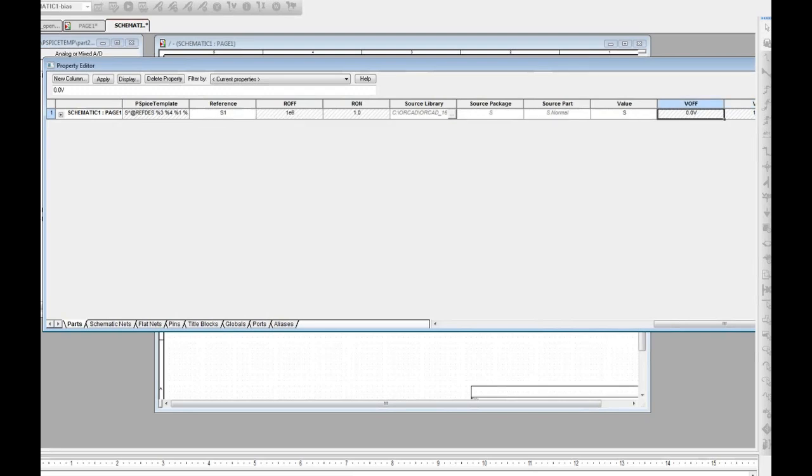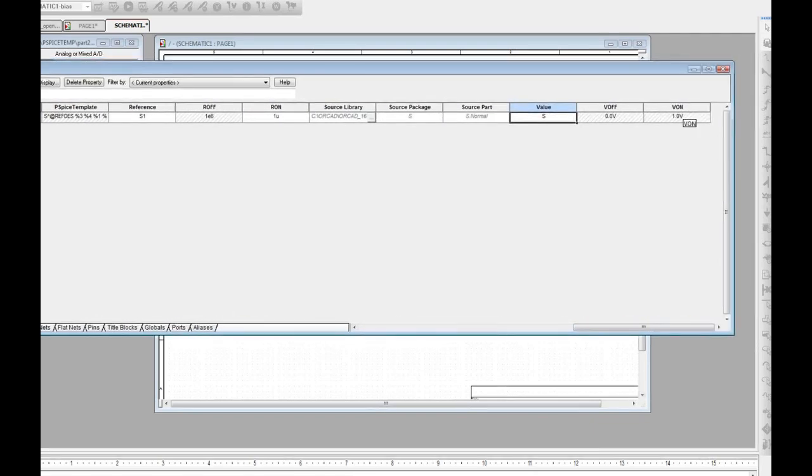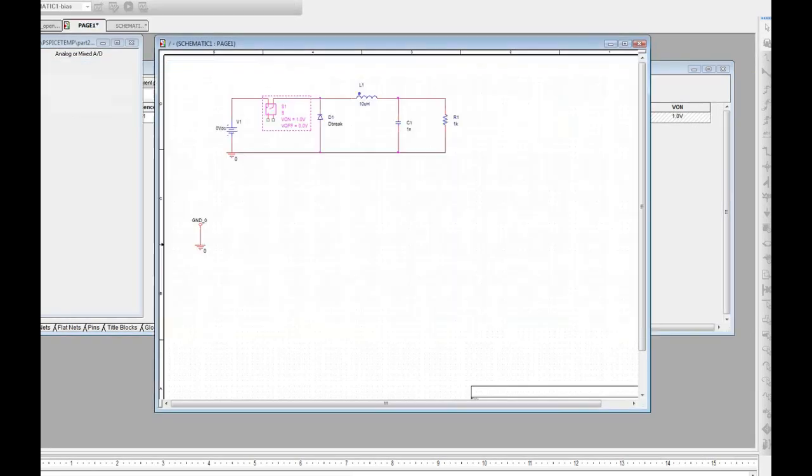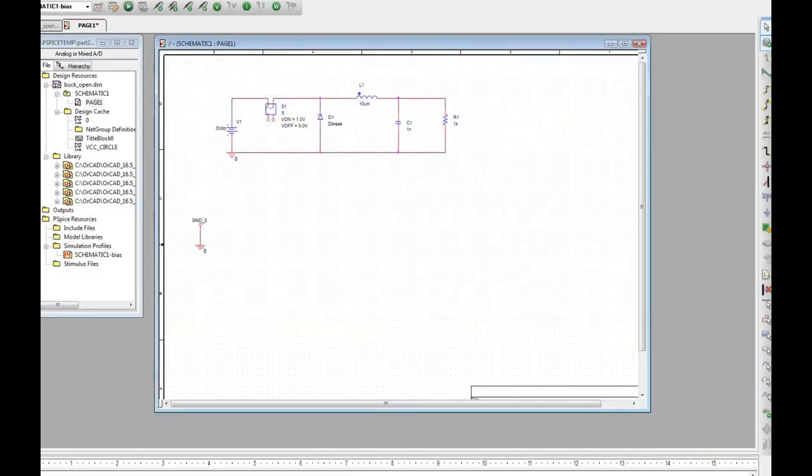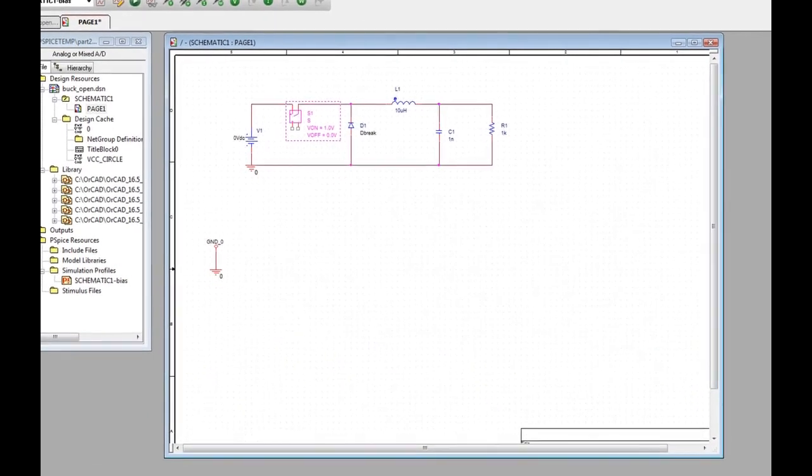For example, the on-state voltage is not shown, but here's the off-state voltage, the on-state resistance, the off-state resistance. I'm going to make that on-state resistance, when the switch is actually closed and on, 1 micro ohm. And micro in PSPICE speak, as I mentioned, is a U. And then we'll leave 1 mega ohm for R off. It's assumed to be ohms, of course. And we'll look over here at V on, which is 1 volt, and we'll leave that as it is. That's good.